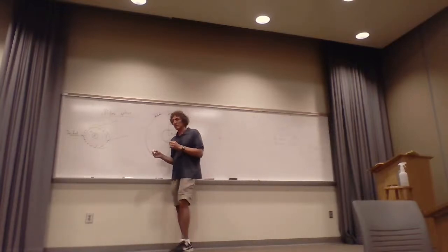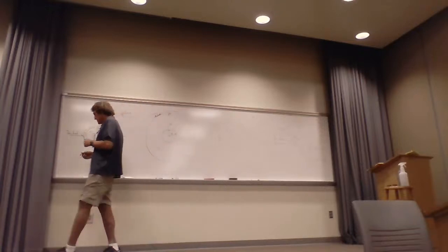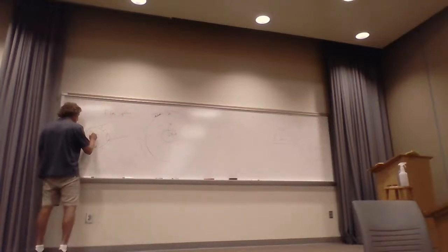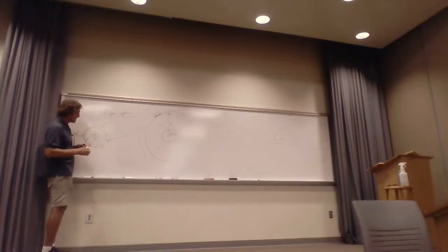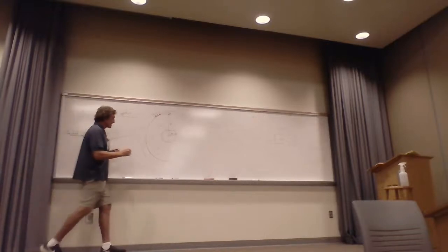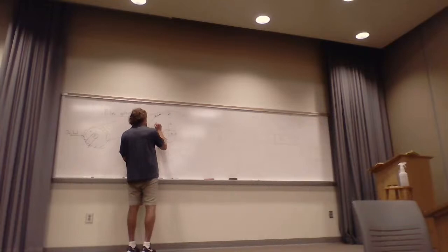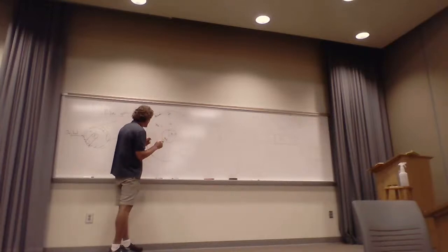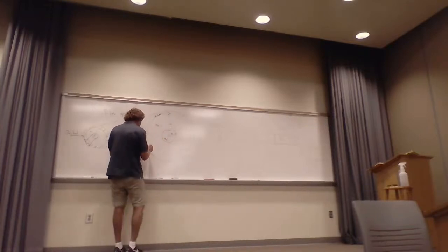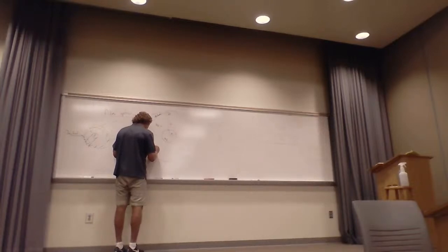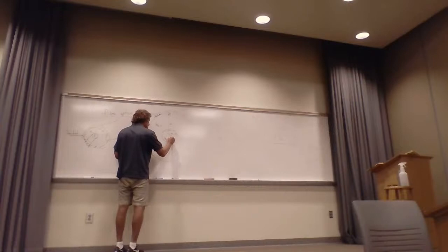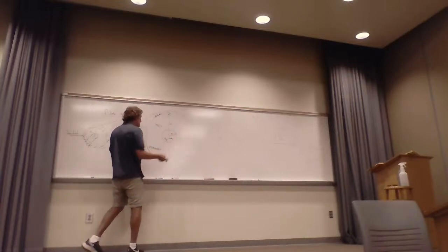The core material is the one that has the highest index of refraction. And in his book, he shows you a picture of it. It's got a radius A. It's got some intrinsic or some refractive index N sub F. Here in the cladding, you have N sub C. This is the cladding right here. This is the core. And that's the jacket.